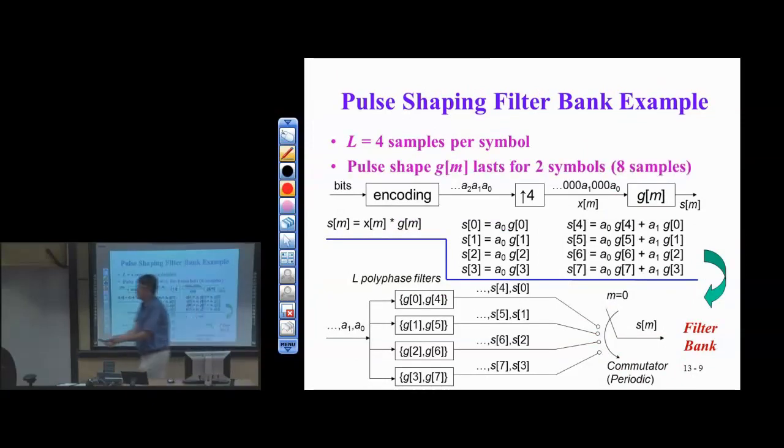Now, if you look at this standard way to do interpolation in discrete time, it turns out to waste an awful lot of multiplication and addition operations. So let me give you an example with 4 samples per symbol period. When I use the word symbol, it could mean symbol period, it could be symbol amplitude, it could be symbol of bits. So 3 different ways, I suppose, it could mean something. In this case, it's a symbol period.